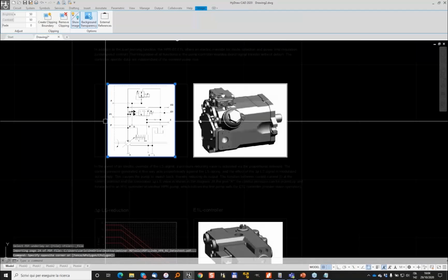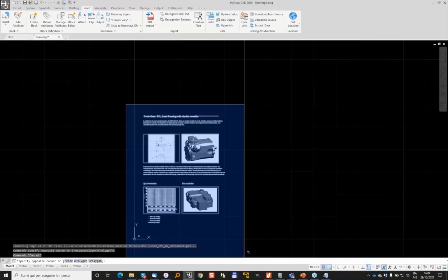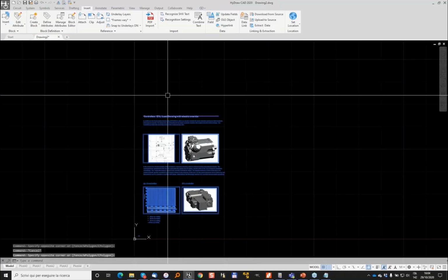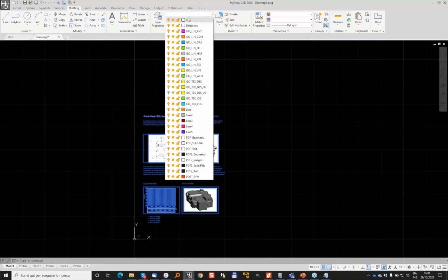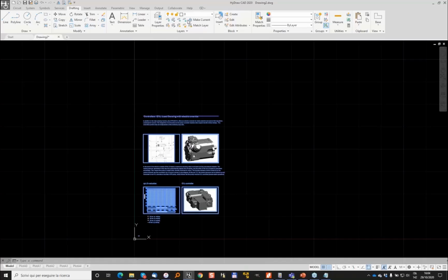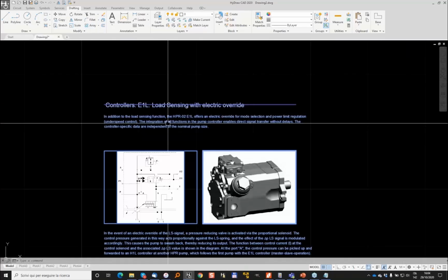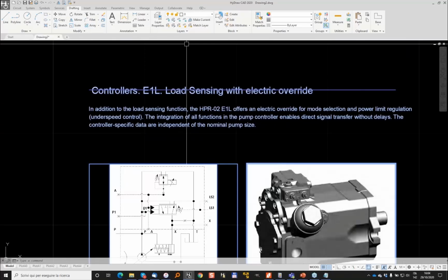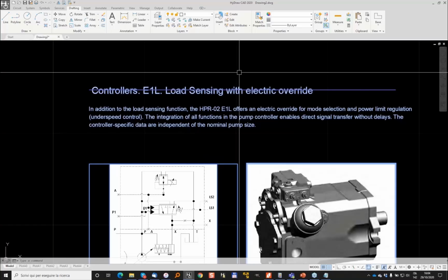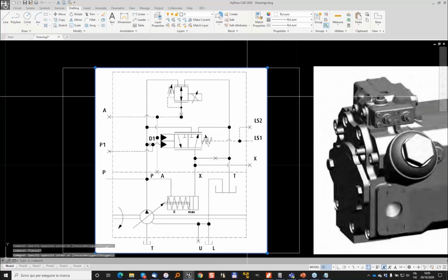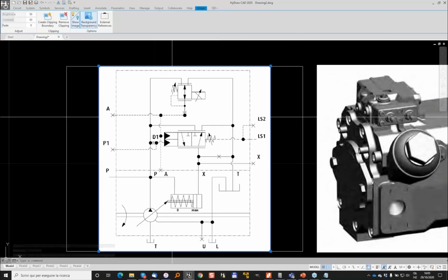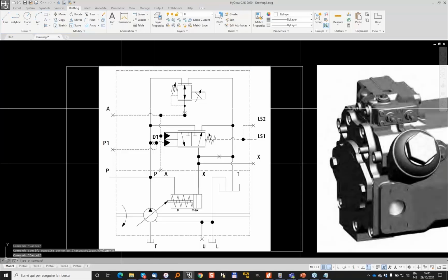Let me change a bit all the colors. To change the colors of drawing entities, you select everything and put it all in a layer; maybe layer 0 is fine. Everything will be white. Layer is located in the Drafting menu. As you see, in this case, the drawing is an image. It's not made of lines. In this case, really nothing can be done except maybe using the frame to create entities on top of it.